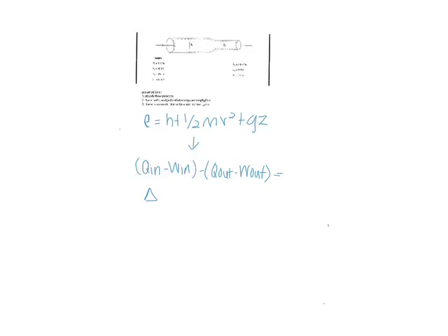Next, by substituting the total energy equation into the energy balance equation, we will get Q in plus W in minus Q out plus W out equals to change in enthalpy plus change in kinetic energy plus change in potential energy, which Q in, W out, change in kinetic energy and change in potential energy are all equal to 0, whereas for Q out, we can see that there is temperature difference between the inlet and outlet temperature, so this indicates that there is heat loss. With that, we are left with negative Q out equals to change in enthalpy.